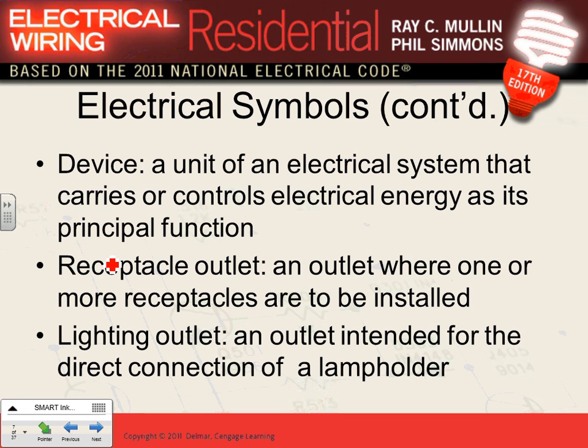Okay, device and receptacle. Devices, this is by code called devices, guys. Devices, they control power, but they do not consume it. Okay, these are called by code devices. What's the difference with device and outlet? A device does not consume power, but controls power. Everybody knows that one? So that's your device business. Control power but does not consume it.